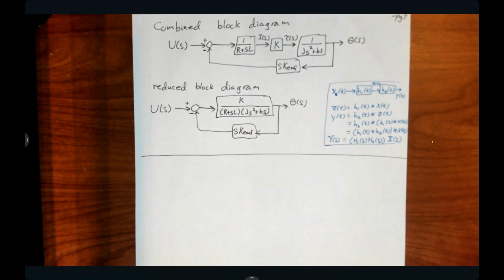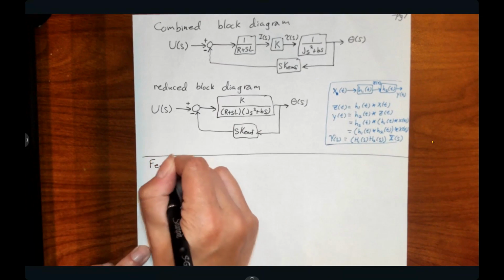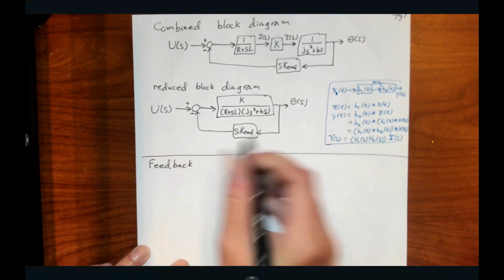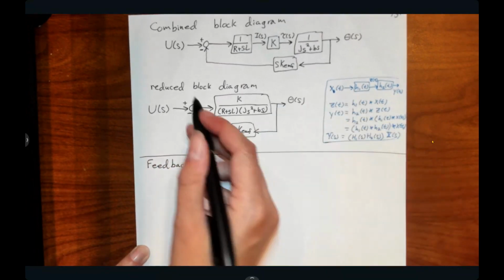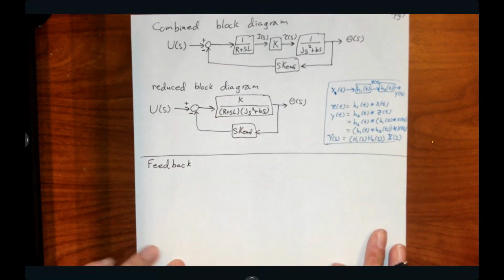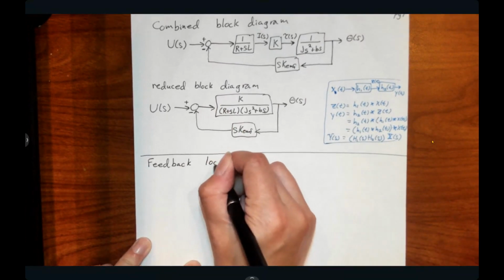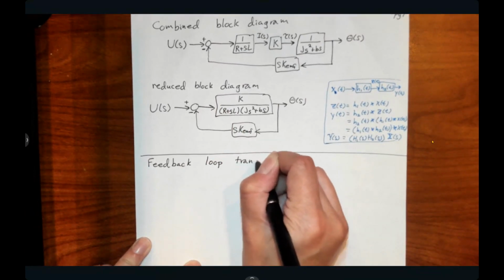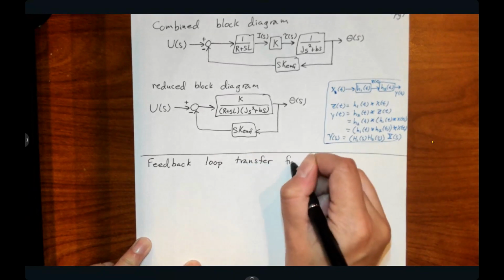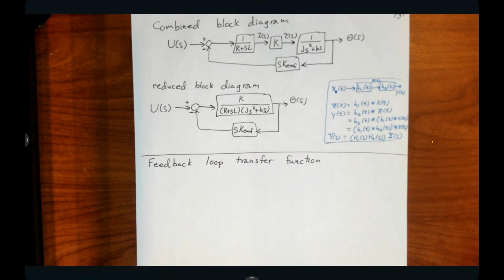And so this comes to what I led with, the description here, which is a feedback. We call it a feedback because you have this output feeding back towards the input, or further back into this system that we have represented. If we have something that looks like this, we can reduce it to a single transfer function.